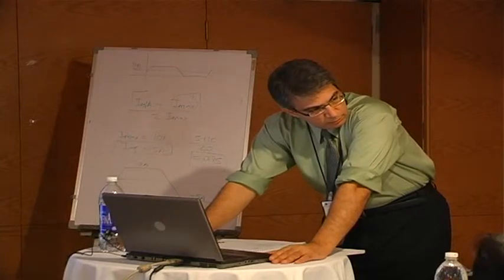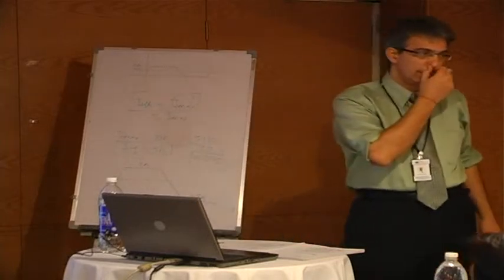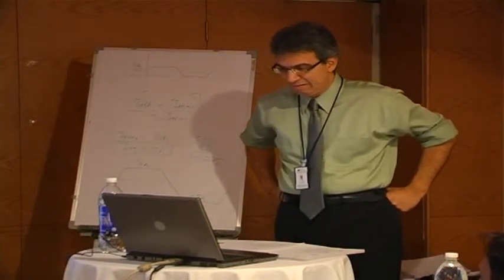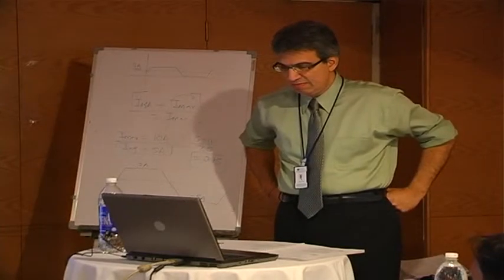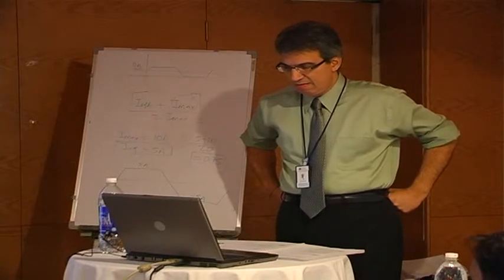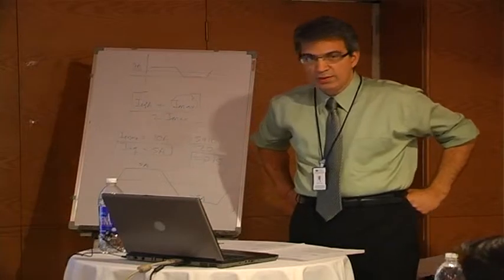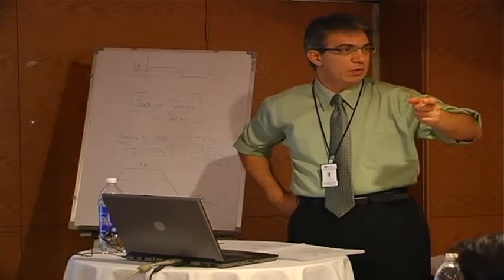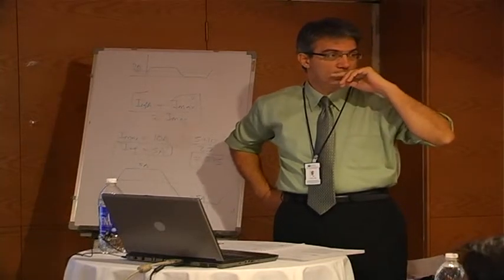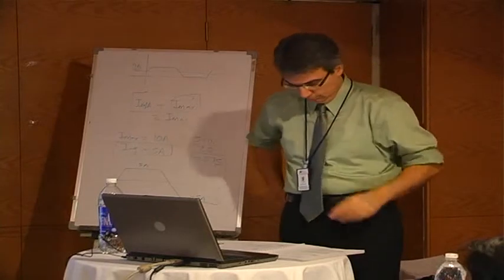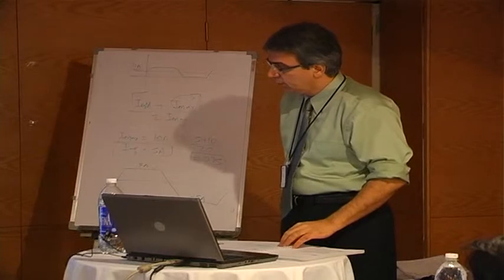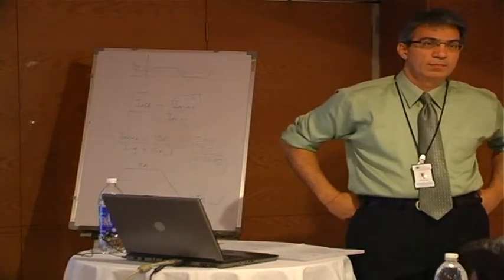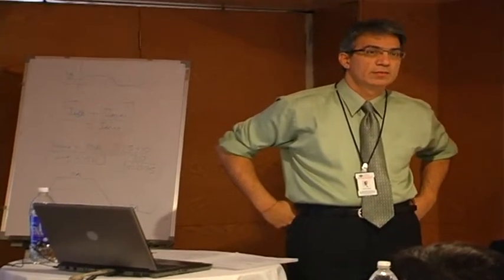Physically giving the reference signal here, through the parameter file, just inputting it. Yes. You're just telling it, give me 5 amps. That's right. So this one becomes a little bit more time intensive because we have now got a closed loop. We have not only incorporated all channel PWM, we also incorporated a closed loop system. So the speed then is a function of time? Constant speed. So the closed loop is for what? For the currents. Yeah.